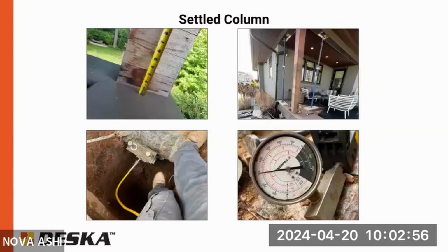I mean, I've heard some numbers, obviously they can't test a pier for 500 years, at least easily. But I've heard numbers from 700 to 1,000 years is what they project how long the pier would last in the ground, assuming there's not any corrosion or chemicals or something in the ground that's going to deteriorate it faster. But in normal galvanized steel, very, very long time. So what would the failure mode be without the corrosion you were saying?